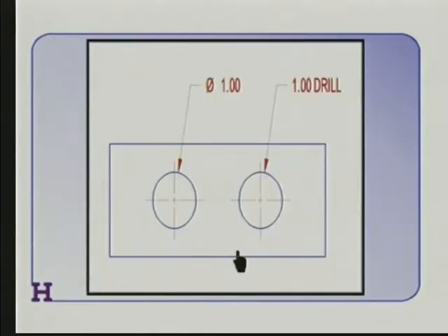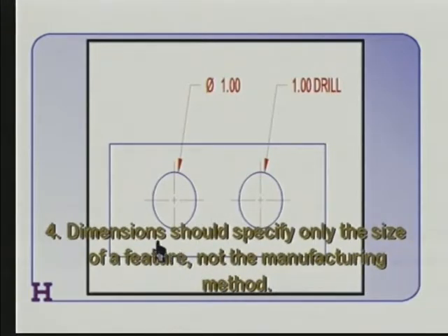Principle 4. Dimensions should specify only the size of a feature, not the manufacturing method. Now, you may find some old textbooks that have a dimension like this for a hole. Such and such size drill. Well, you need to keep in mind that engineering drawings, once they're signed off, become legal documents, and they have to be followed exactly.